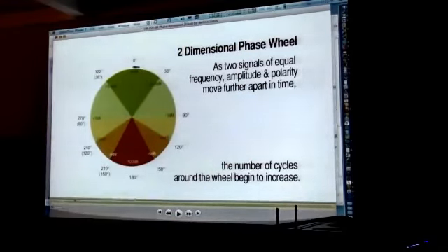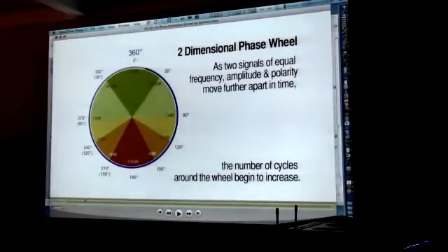1 millisecond. So this means that if we play an audio signal through an electronic processor with 1 millisecond of delay, and we perform a frequency sweep, the sweep will show that the phase will increase and will be exactly 1 cycle at 1K. And if the sweep continues, the second cycle will be at 2000 Hz, the third cycle at 3000 Hz, the fourth cycle at 4000 Hz, and the fifth cycle at 5000 Hz.